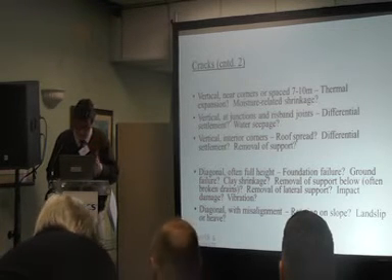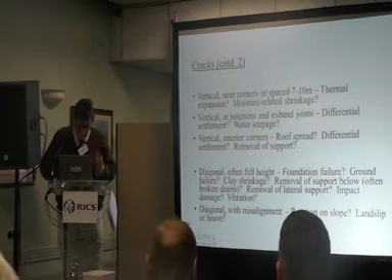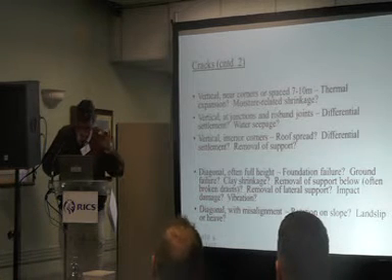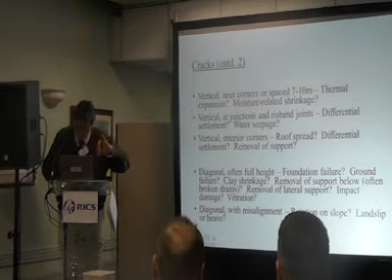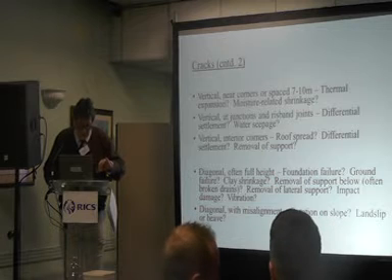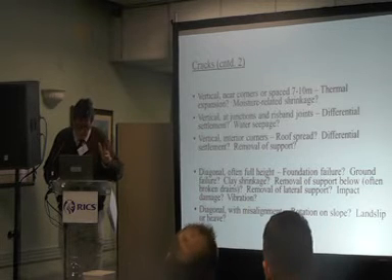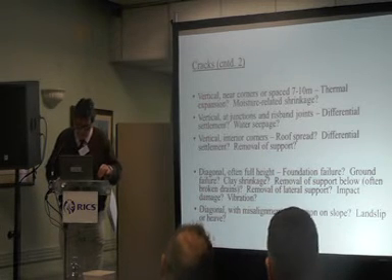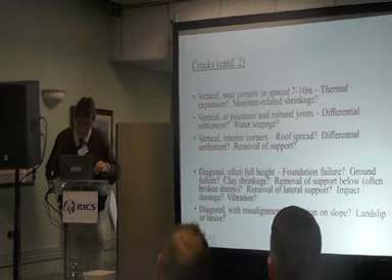Inside the building, if you get to a corner and you find that perhaps a partition wall has dropped, you might want to look at roof spread, you might want to look at differential settlement, but very often it's removal of support. And what day is it?